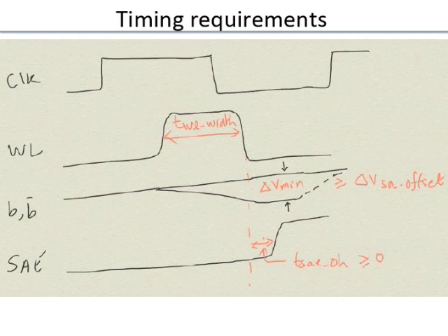And here one of the things is that the actual delay you need really depends on the memory cell and the process shifts. You cannot say it is so many nanoseconds, because a different chip will have a different delay. So you need to have circuitry which tracks the actual conditions of that chip. Whenever you have to do that, you need to use a replica circuit which will essentially sample the same process condition as the main circuit. But I can fetch it from my original memory cell only.